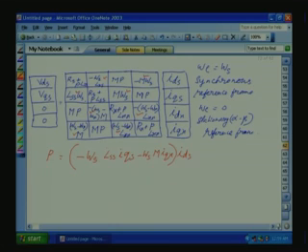Then the Q axis stator, again this will be equal to omega s LSS IDS, that is this voltage term. There is another voltage term here, plus omega s m, and the current is IDR. This is the voltage term. So, multiplied by IQS, it is the power at the stator.